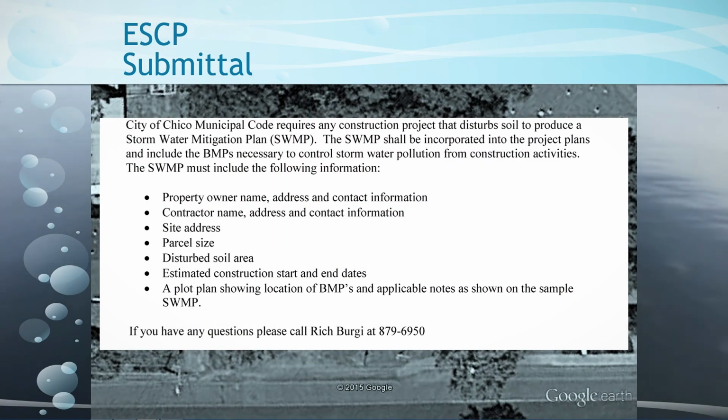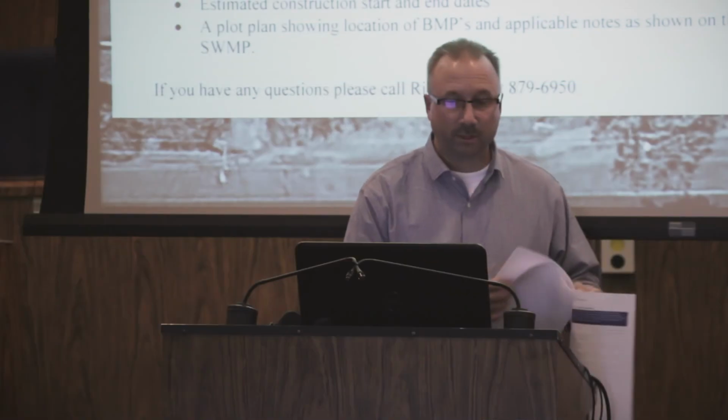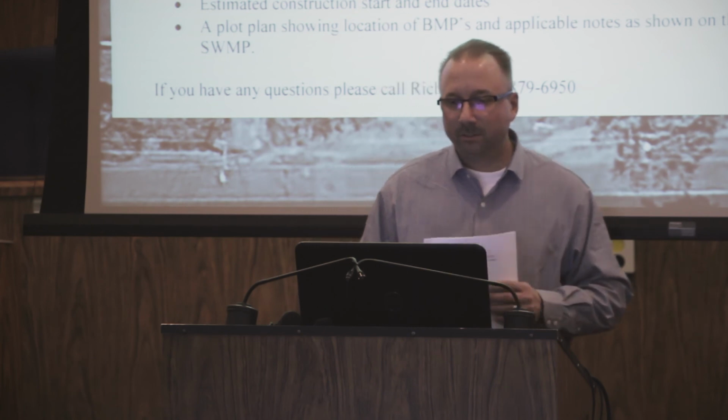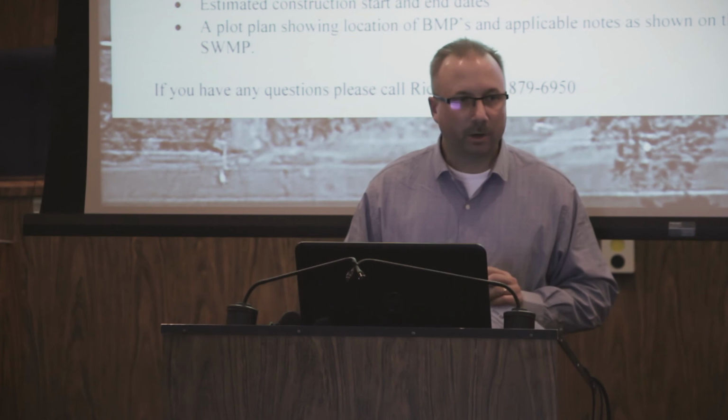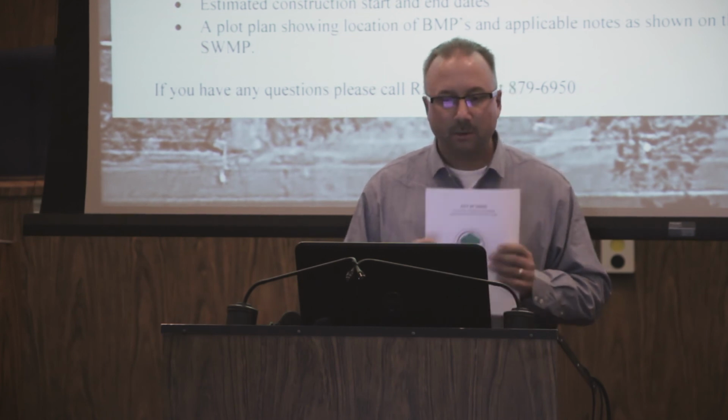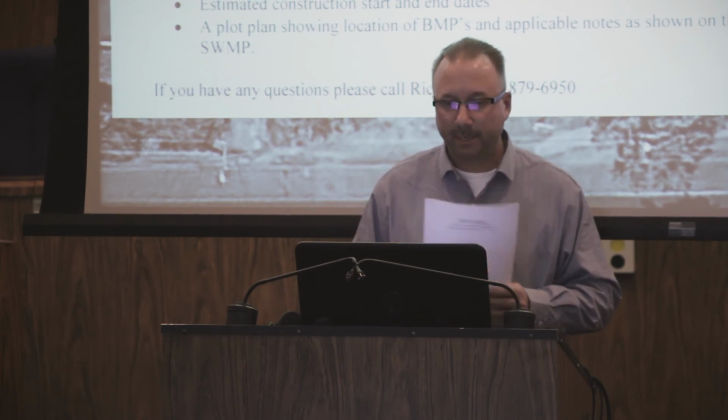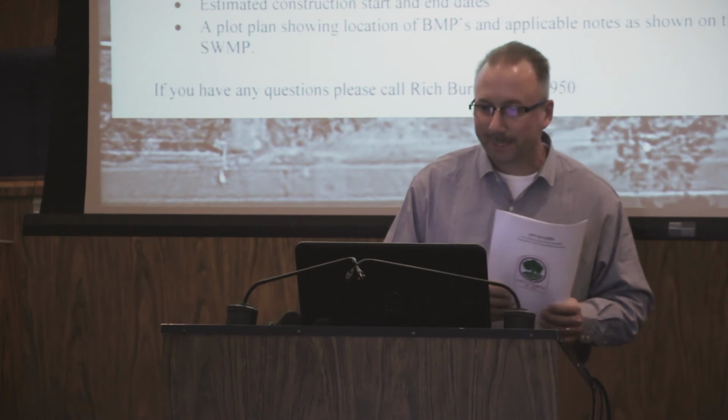All right, now just some notes on the submittal process. So again, this is for the smaller project that is using this worksheet. So this worksheet is going to be part of the submittal, and they'll need to turn this in. But in addition to this, they need to produce the drawings that go with this. And the City of Chico calls this a stormwater mitigation plan, or a SWMP.